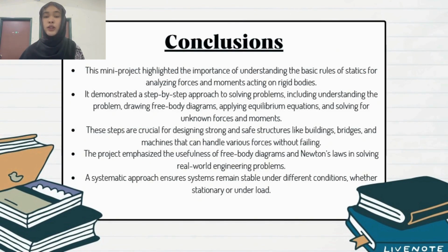So firstly, we need to understand the problem first, and then we drew the free body diagrams, which is FBD, and then we use equation to find equilibrium, and finally, we solve for unknown forces and moments. These steps are very important in designing safe and strong structures like building, bridge, and machine that can handle forces